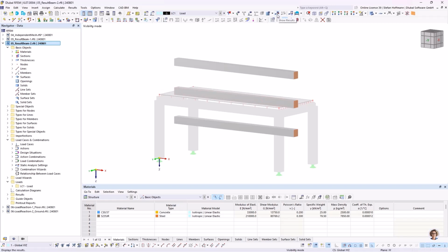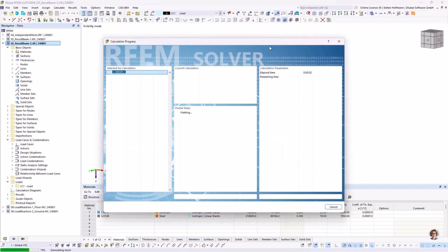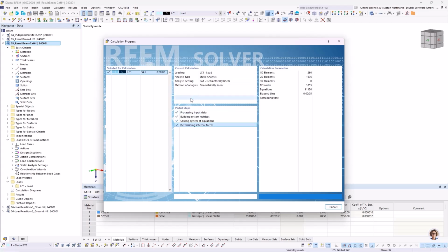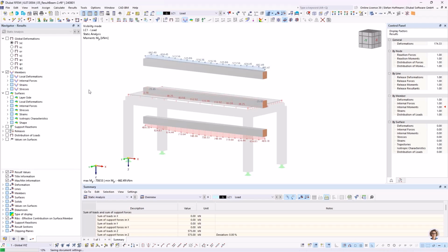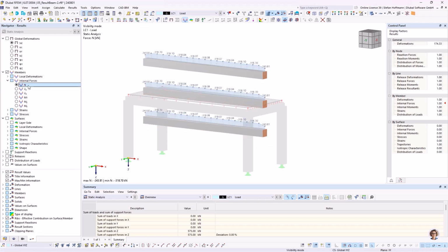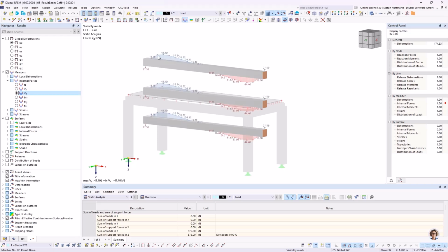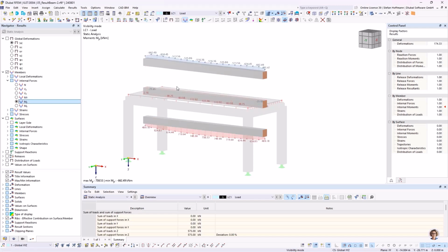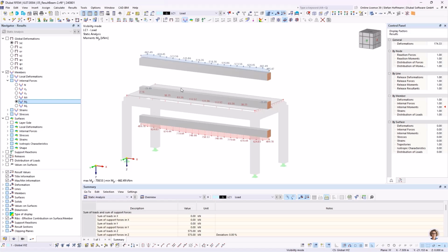And what I would like to show you in this example is that, for the inner forces, the position of the result beam is important. If you check the internal forces, the first 3, normal force, shear force, and the second shear force, you can quickly see that the position of the result beam does not have any influence on the result displayed. But if you check the 4 moments, most likely we will only compare the bending moment about the strong axis, you can see that the result is influenced a lot by the position.